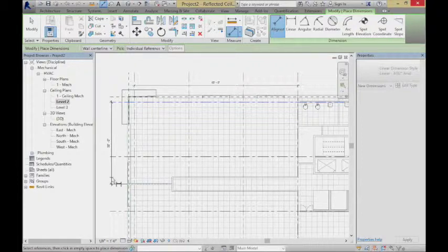I want to put just a few more in there so that it sounds like I probably could get by with 2, but I'm going to go anywhere from 2 terminals to 4 terminals. And it sounds like anywhere in there is going to be okay. What's the difference? If I have fewer terminals, I'm moving less air. The air is a little bit stiller. If I put more terminals in, I'm moving more air. The air is just moving its pressure. So in an office space, 2 is probably fine. In something where there might be some fumes we want to move away, 4 would probably be a little bit better.